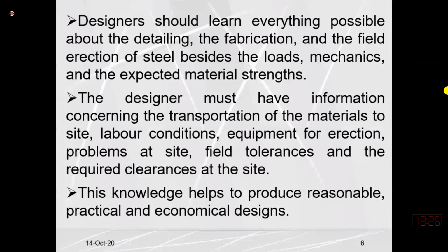Designers must have information concerning the transportation of material to site, labor conditions, equipment for erection, problems at site, field tolerance, and required clearance at the site. Most of these problems occur in mega structures, or a structure where the length of, for example, a plate girder is very large. For example, you have decided a plate girder length may be 10 meters, which means 30 feet.